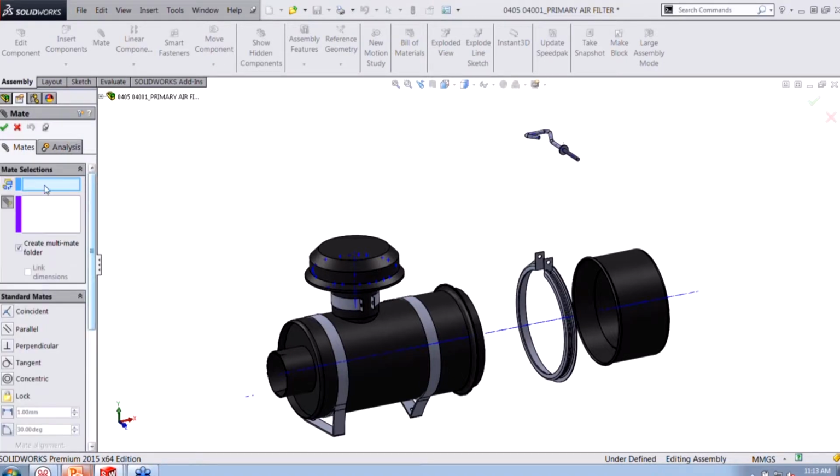And you'll get a common reference, which will be like my main axis. For example, say it's going to be this one here. And then afterwards, for your subsequent references, you'll select the other ones. Then you'll click on these, and they'll appear in this box. You just make sure not to press OK, because that'll complete the mate. You'll just keep left-clicking until you're done, then press OK.